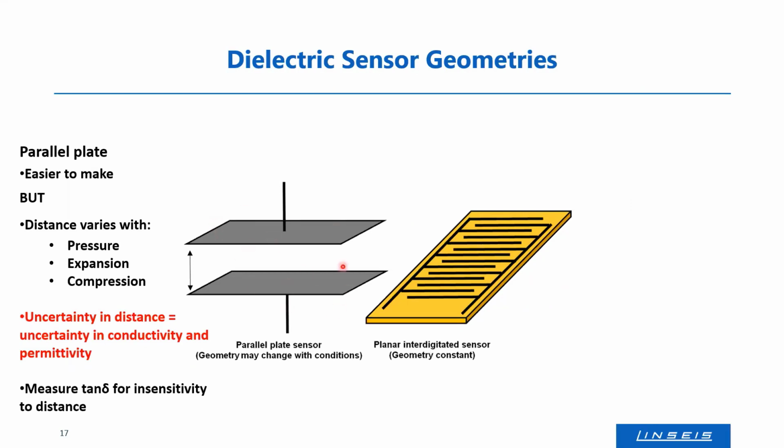And for that reason, no parallel plates are used to monitor the cure, but so-called interdigitated sensors, like shown here on that slide. These are usually foil sensors, so thin Kapton foils, and inside these foils you see these wire structures, and on the left-hand side you have an electrode, and on the right-hand side, and they are interdigitated.